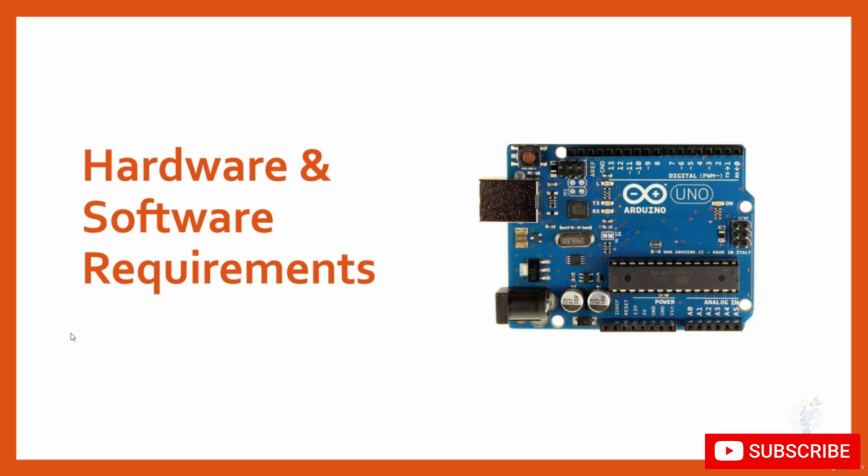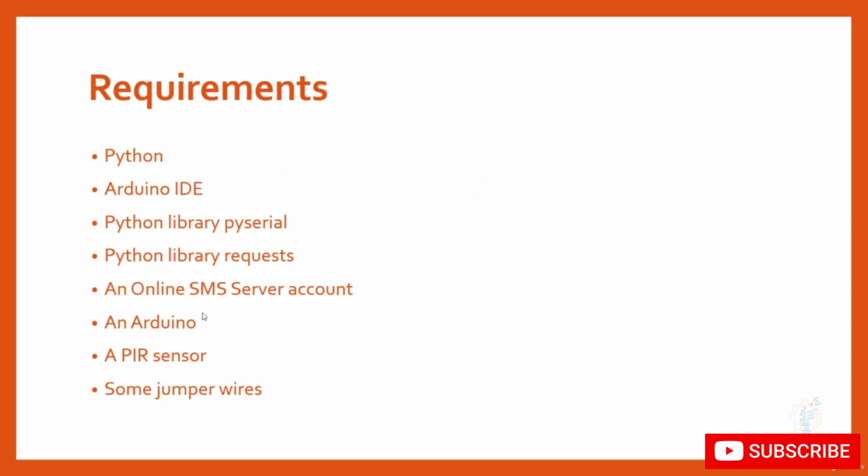Hardware and software requirements. Now, as you know, we are going to use Python and Arduino. So, as hardware requirements, you will need an Arduino board. You will also need a PIR sensor, which is basically the motion detector sensor. If you don't have one, you can replace it with a simple toggle switch, just to send on and off signals to a certain pin on the Arduino board.